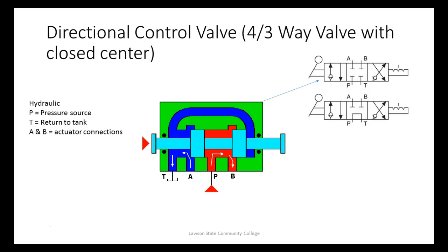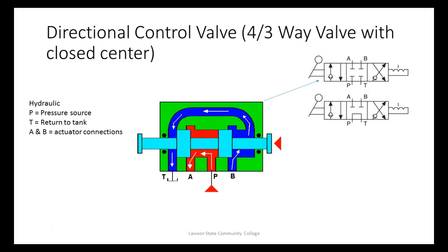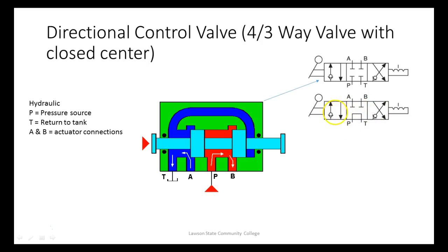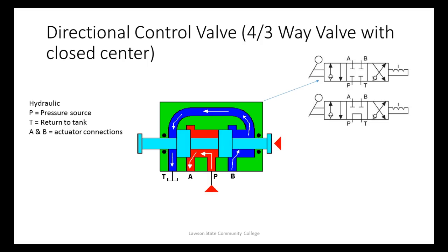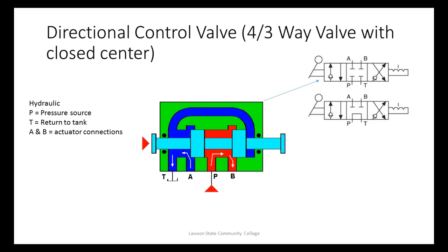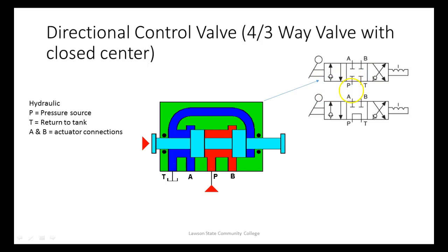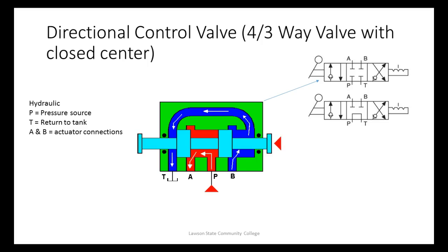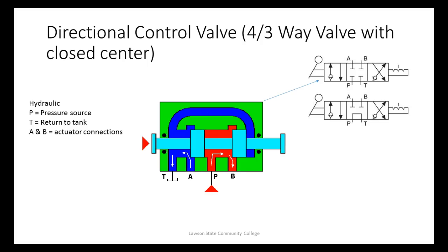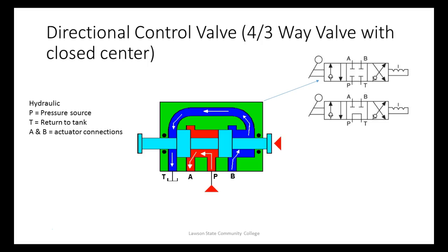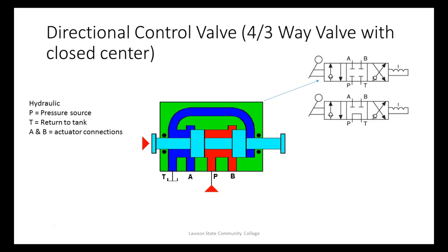This is what we would have to use in pneumatics. We use a lot of this in fluid power because if you're not using the pressure, then what you would like to do is return it to tank. But in pneumatics, we can't return it to air because we lose our compressor. So these are all hydraulic. So here what this would do, if we put it in the center position, it would maintain pressure, right? You understand that? But it would lock the actuator. So the actuator wouldn't be able to exhaust and the actuator wouldn't be able to move. We couldn't extend it or retract it.